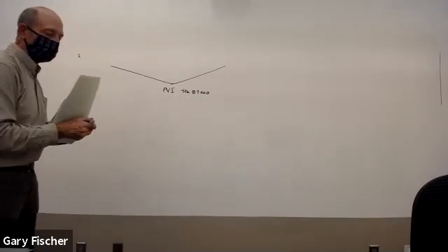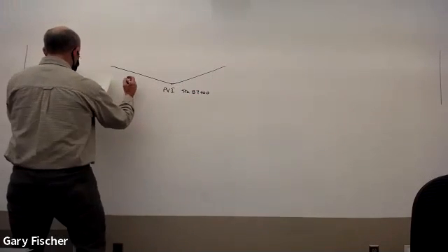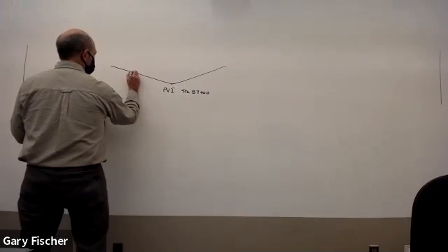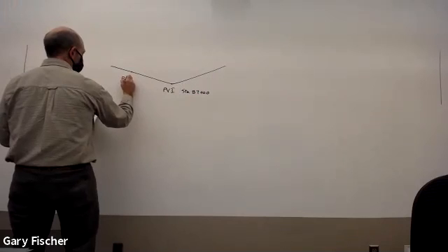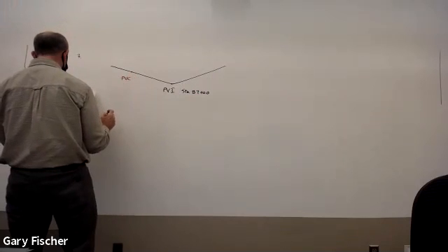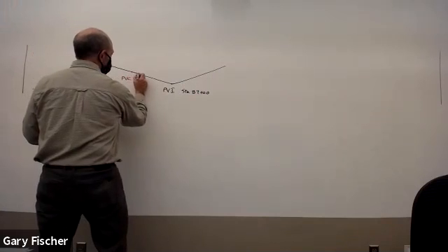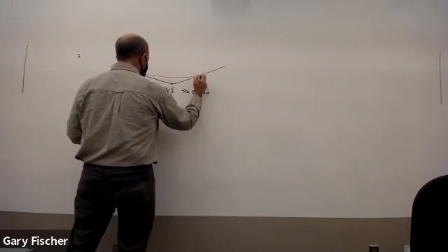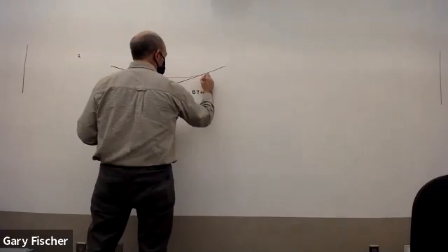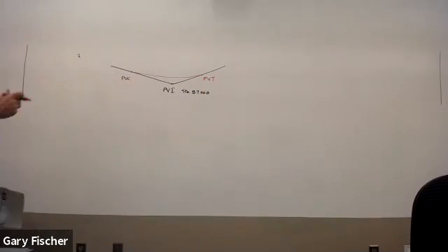So it comes out like that. Then there's a curve between it. We start out here at the point of curvature, but here they call it PVC because it's a vertical curve. It goes through something like this. It makes a gentle curve and you end up at the PVT, point of vertical tangency, on the other end.